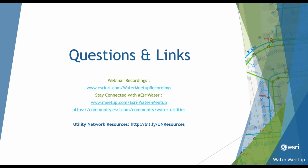Thanks. Our next question is specific to servers. I know you mentioned having a server dedicated to the utility network extension. Why is this required, or is it not required? It's just a recommendation. It's not required. So if you're a small organization and you have a base deployment of ArcGIS Enterprise and you're only serving out a couple of users, it's certainly possible. You can license the Utility Network Management extension on that ArcGIS Enterprise. We just really are recommending that you, for workload separation and other reasons, have a separate GIS server specific to your utility network. But that's really just a best practice recommendation. It's not a requirement. Thanks for clarifying.